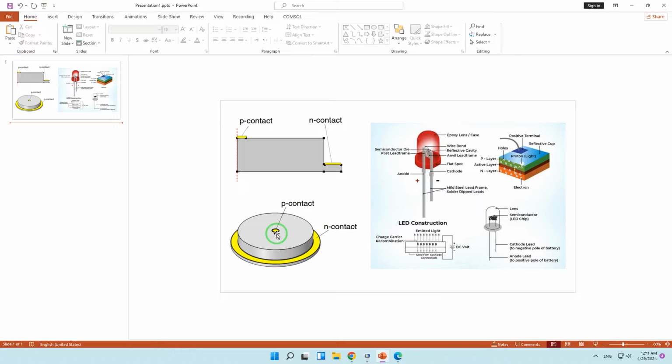An Auger recombination feature has been added to include a non-radiative recombination mechanism. This is only one possible non-radiative recombination mechanism. In reality, a variety of other processes may be present, such as lattice impurity scattering and phonon interaction. However, for the purpose of this demonstration model, Auger recombination is sufficient to capture the important behavior that the efficiency of the radiative emission drastically reduces with increased current density.